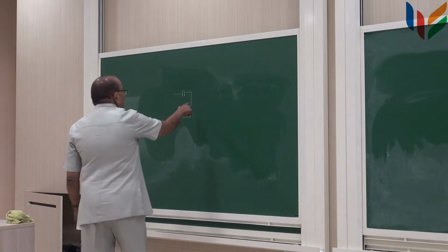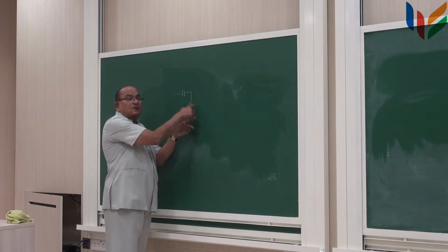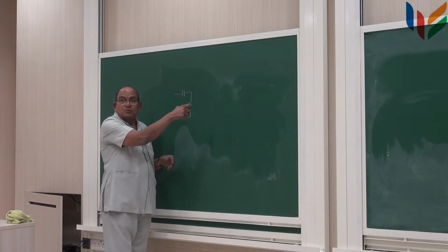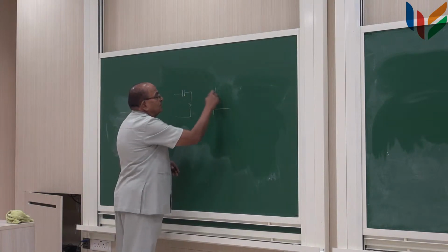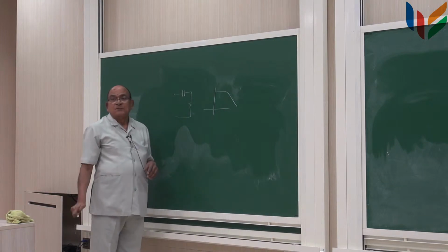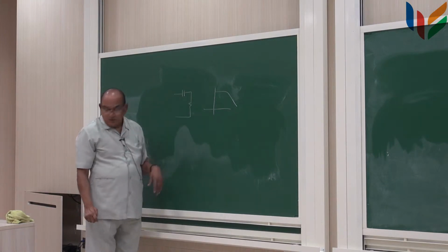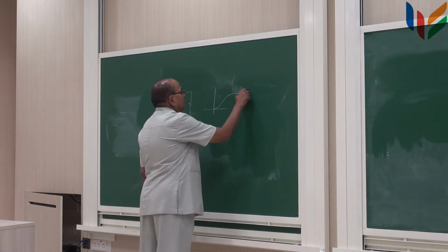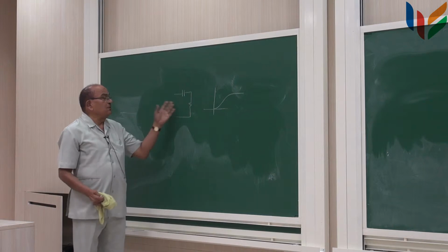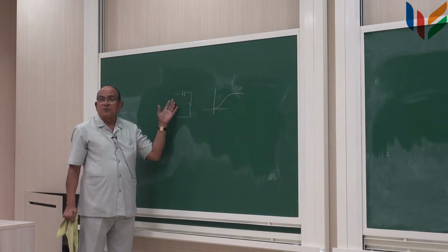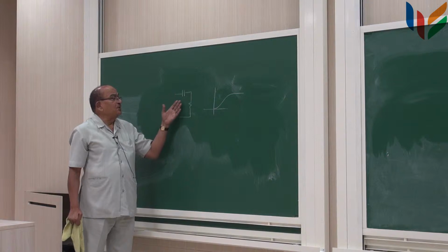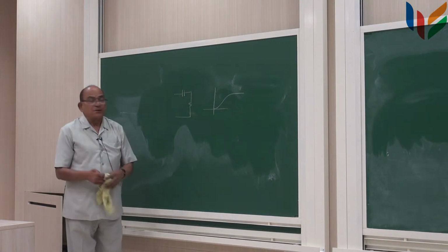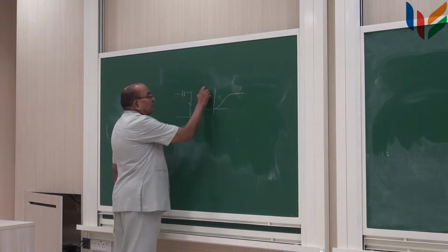The output voltage will be equal to this divided by the two impedances, right. So, it has some amplitude function which will be like this. At S is equal to 0, no, I am sorry, at S is equal to 0 it is open, so there is nothing transferred from here to here. At S is equal to infinity it is a short circuit, so it becomes equal to 1. So, this is how this variation is in terms of the magnitude.